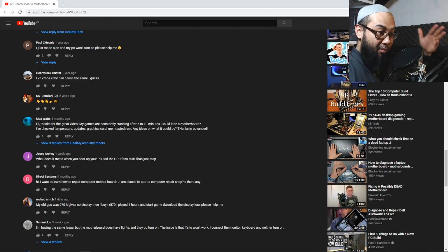Watch that. Let's take some live questions. Hacker TV, yes, it's LGA 1155. Okay, you've told us your socket, which is LGA 1155. Fantastic. What you haven't mentioned is what happens when you put back your previous processor, or put in a different processor instead of this upgraded one. You haven't told us, does it still do the same thing? Because if it does, then yeah, probably your motherboard is dead. If it's not, it's probably a compatibility issue. Okay.